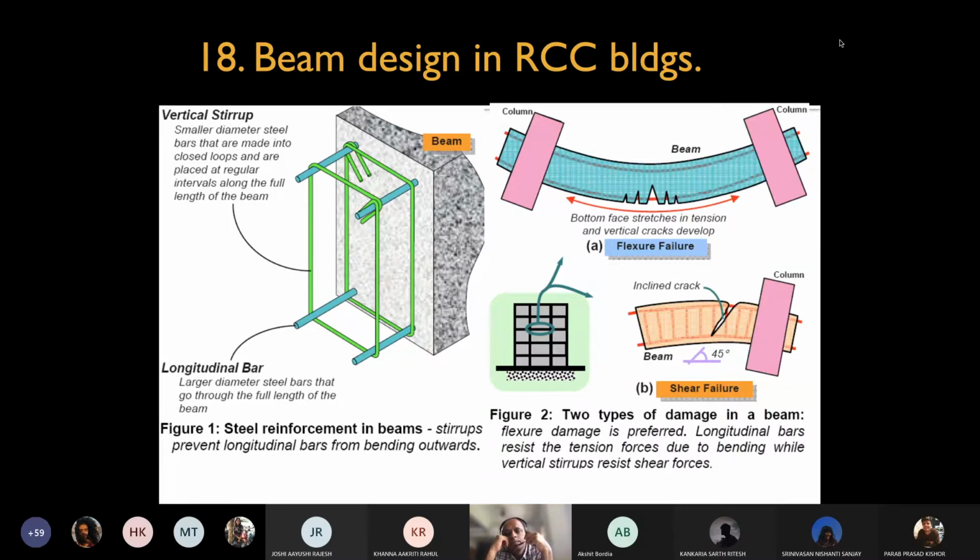I don't know if somebody mentioned to you, but when we were students, there was this building in Worli called Poonam Chambers. Poonam Chambers was one case where the building was constructed as a flat slab construction. The entire building was flat slab construction. Of course, this was not related to earthquake, but it is important to drive home the point: what is the difference between shear failure and flexural failure?